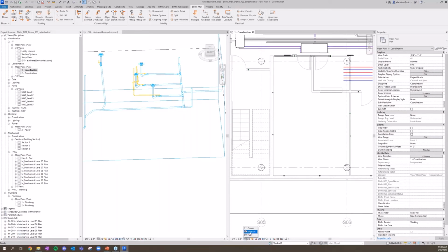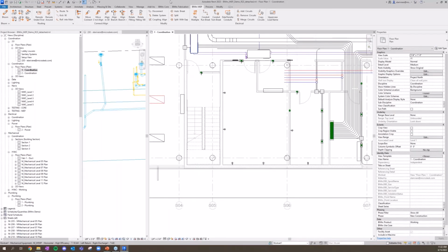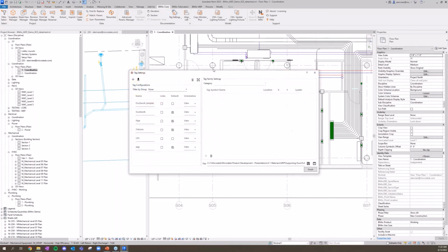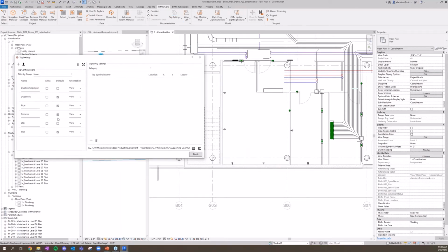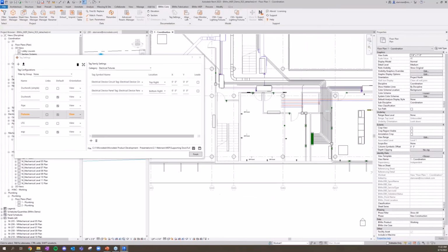I'm going to swap us down to a medium view over here while we take a look at these. Why don't we just drag this to the left a bit? So popping back into core, I want everyone to see this tag settings command. Tag settings allows us to build out tagging profiles that we can then use to tag multiple tags on a single element at a time. For me, that means jumping in and tagging all of those panels all at the same time.